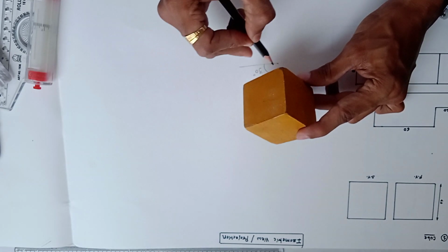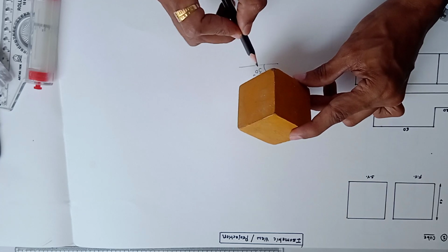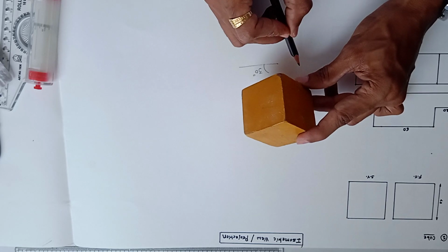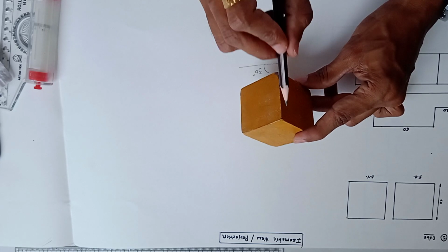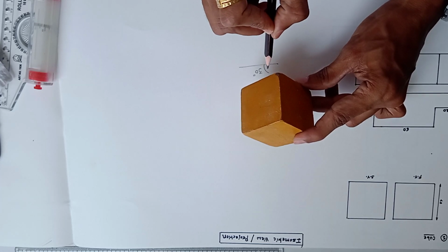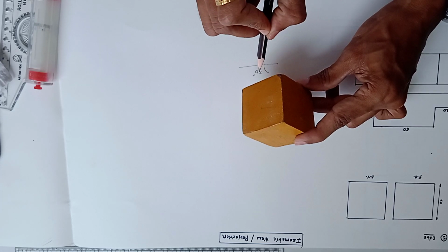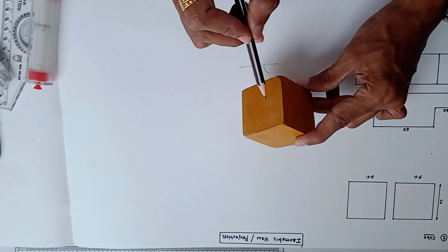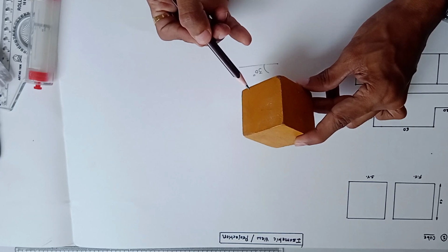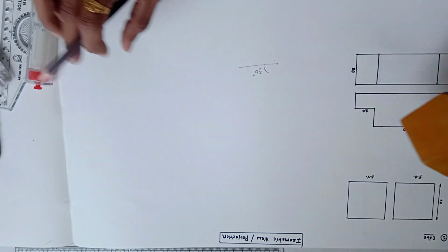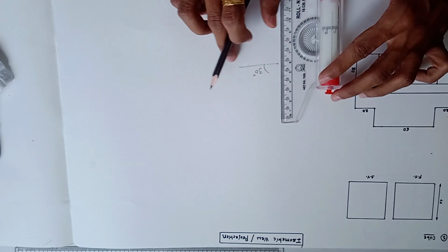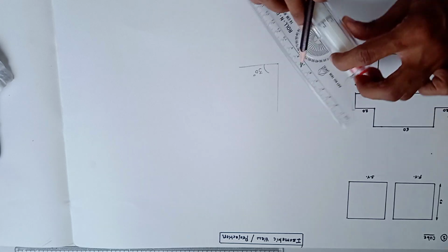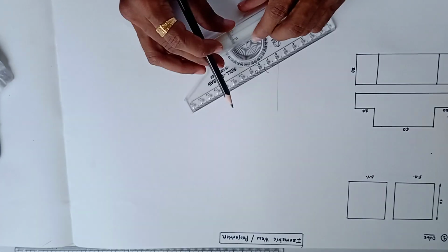Again, this line will appear as a straight line at an angle of 30 degrees. So these two major axes will be at an angle of 30 degrees, and the third axis, its angle is 90 minus 30, so this angle will be 60 degrees. Actually this is 90 degrees, but this 90 degrees is converted into 60 degrees after taking the projection. If I draw the projection, this is your reference line, then this is the vertical axis of the object, then from this we will draw the line at 30 degrees.